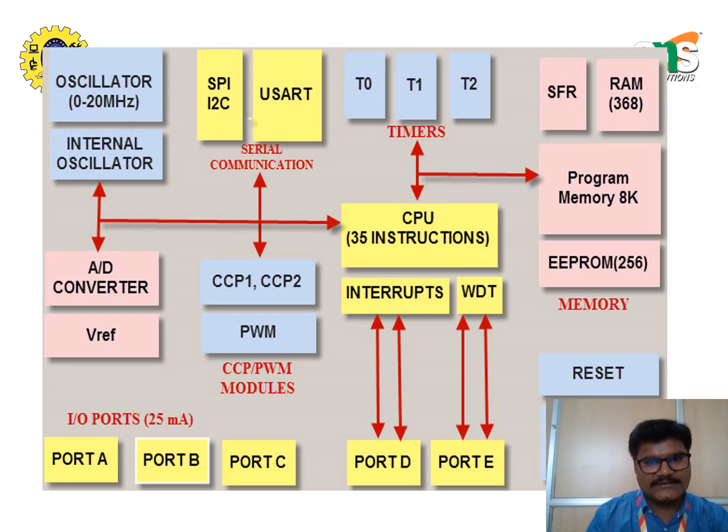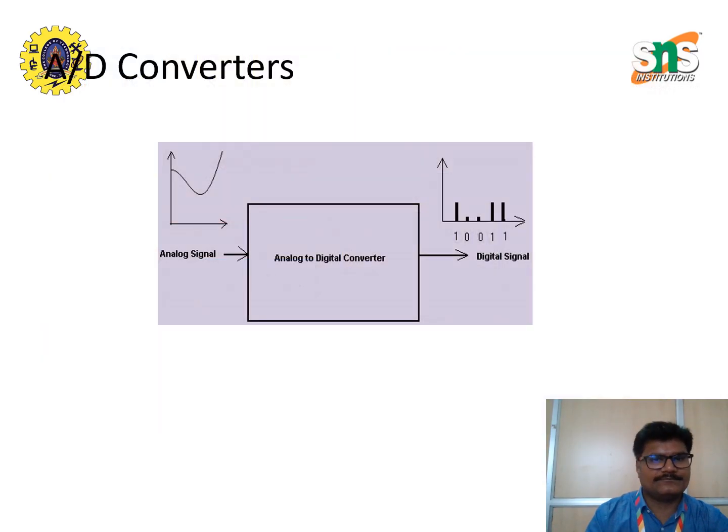It supports 20 internal and 3 external interrupts to prioritize the task, enhancing the multitasking capability. Then comes serial communication. It transfers data one bit at a time over channels, commonly used in USB, GPS, and Bluetooth systems. Then coming to the oscillator, a crystal or RC oscillator generates precise timing signals for the microcontroller's operation.